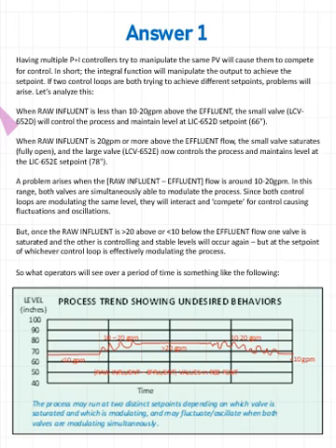But when the raw influent is about 20 gallons or more above the effluent, so we've got a lot more inflow now, the small valve is saturated. It's fully open. And now the large valve really obtains control. It's the one that can modulate or has any impact on the process because the small valve is fully open. So the large valve, that LIC 652E control loop set point is 78 inches.